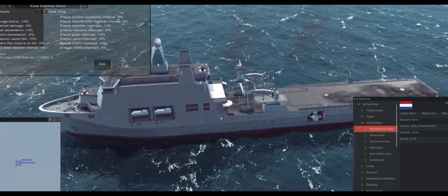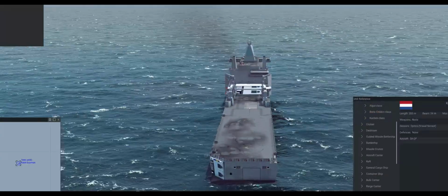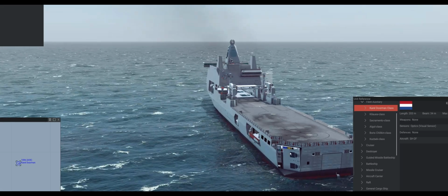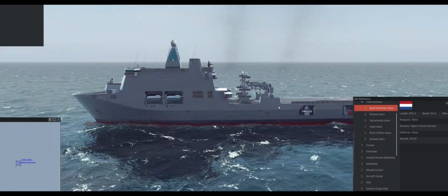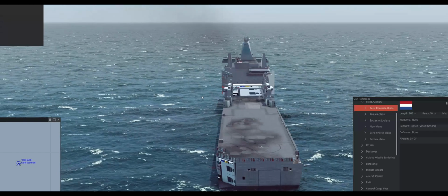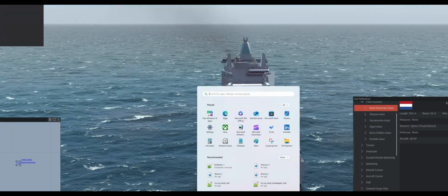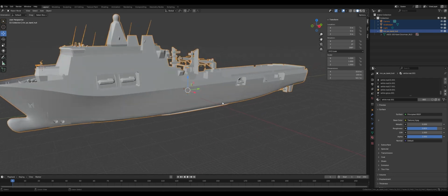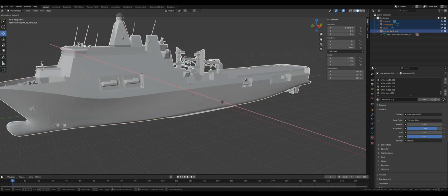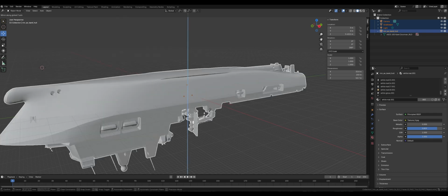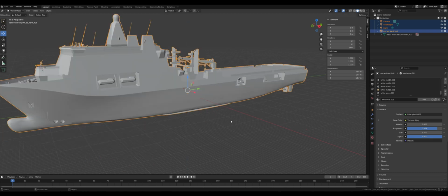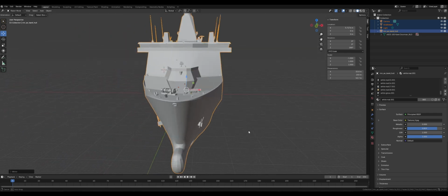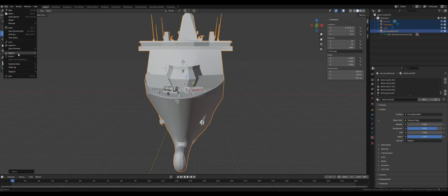That's why you need a purple background. And the backlighting's so weird, and the door is not proper. Also the ship is mirrored. That's something that happens quite often. So what you need to do is you go back to Blender. You're gonna press Alt, Ctrl M, and then on the X axis, mirror X, and then press Enter. Now the ship has been mirrored on this setting.